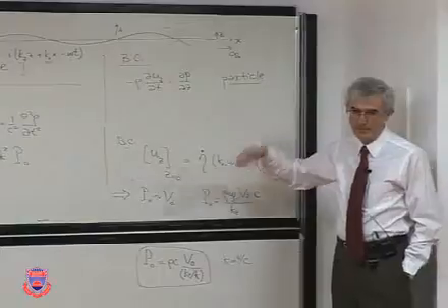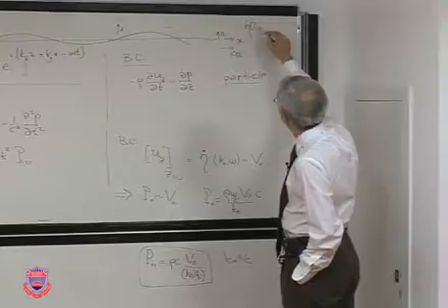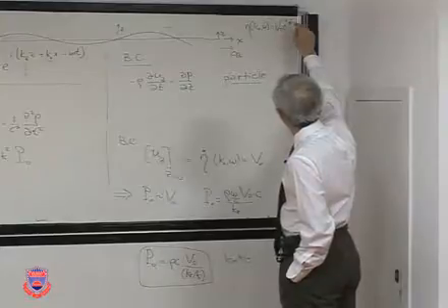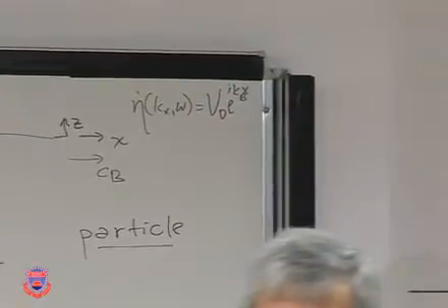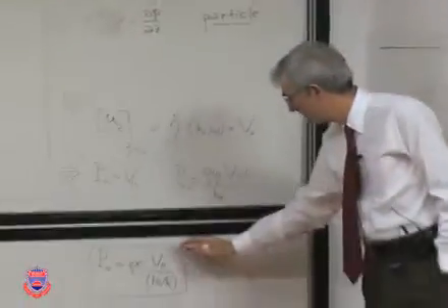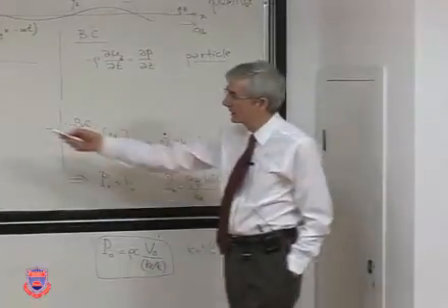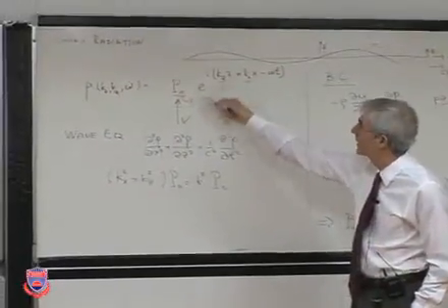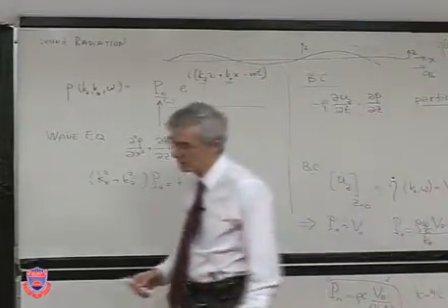It's a given. What we're saying is, here you have a plate that's vibrating at an amplitude. So that's a given. So if you have a plate that's vibrating, what will be the sound radiation? That's what it is. So this is a given, and as a result, we find this. But we still don't know kz. To find that, we require the pressure expression to satisfy the wave equation. And from there, you have a relationship.